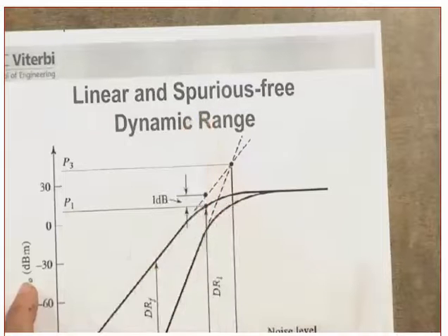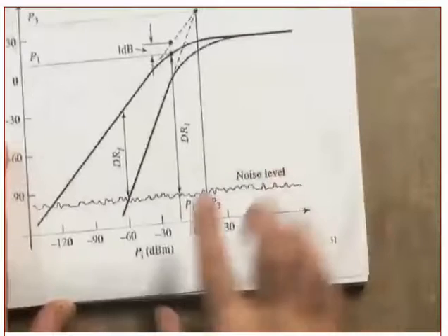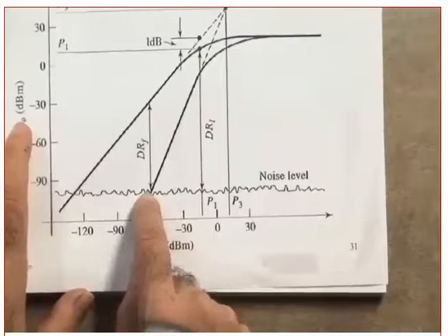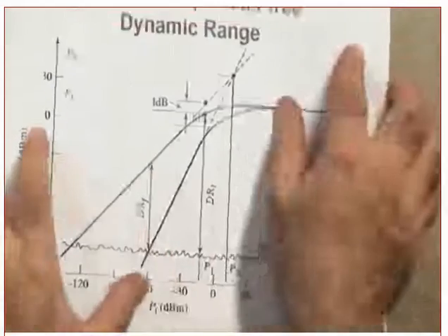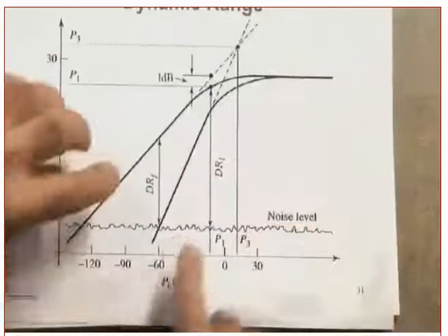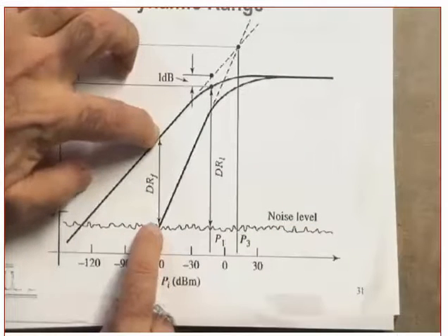An unwanted signal. Not noise. Noise is always there. A spur is an unwanted signal. Is a third order intermodulation a spur? That's a spur. When it reaches this point, it becomes negligible. Do you agree? That is why they call it spurious free.